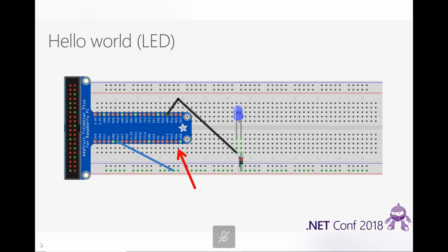The idea is that I can hook a ribbon cable from the Raspberry Pi's GPIO header to the header on this cobbler, and then plug the cobbler into a breadboard, which makes it easy to connect wires to these various pins on the Raspberry Pi and have a visual representation of what I'm connecting to.